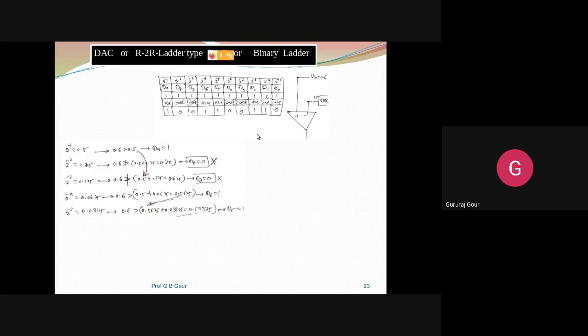Again divided by 2. So what is the last weight? That is 0.5, sorry, 0.75, divided by 2. Or if you want, you can do 1 divided by 8. 1 divided by 8, how much will we get? 0.125. 0.125 or 2 to the power minus 3 will give you the present weight. And the previous weight is what? The weight where the last bit was set. The last bit set was D9, not D8. D8 is 0. So 0.5 will be added with the present weight 0.125, so I will be getting now 0.625.